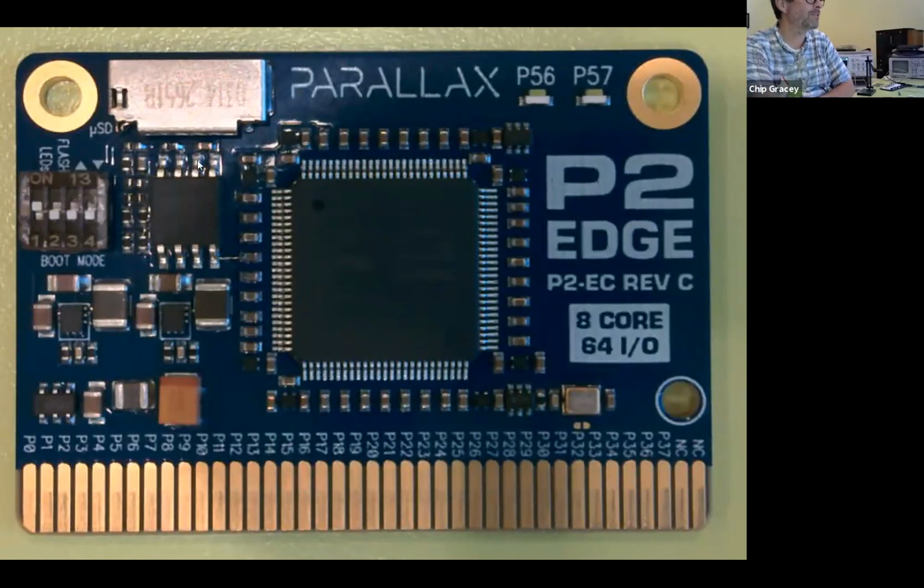Like the P59 pull down resistor is not connected to ground. So this switch effectively doesn't do anything. We'd have to do another little surgery right around here to fill in for that missing via. But we just wanted to make sure we had the big stuff done. So we got it working, but it's not something a customer would want to mess with.